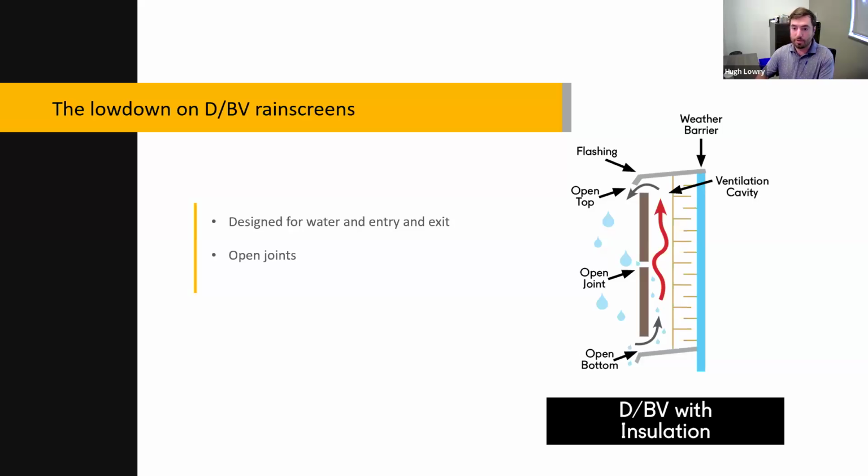Its job is to help water drain from the interior down vertical channels, as well as promoting airflow to evaporate moisture. You have to have fenestrations in the system too, they'll be flashed and detailed to collect and direct water out of the system. And then finally, we have an air-water barrier at the back of the cavity.